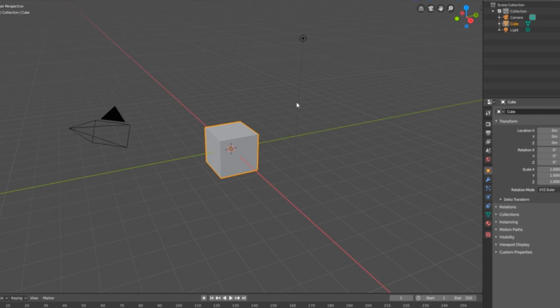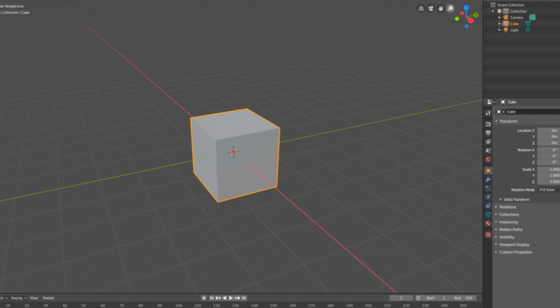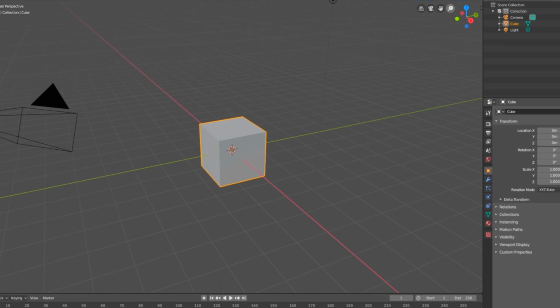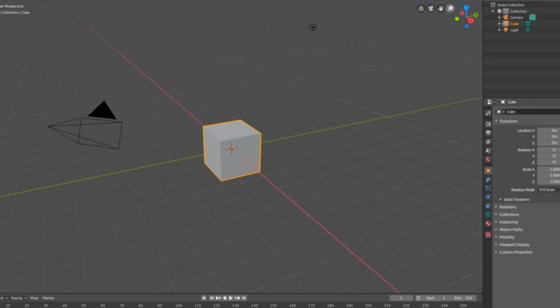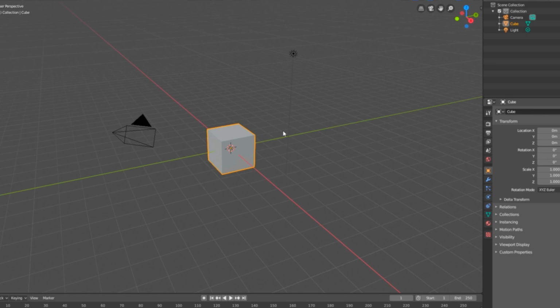The zoom command is for zooming in and out of the scene elements. If we want to use the navigation icon, just click this magnifying glass icon, keep the button pressed, and drag up to zoom in and down to zoom out. The shortcut to the zoom is the mouse scroll. Just spin forwards to zoom in and backwards to zoom out.